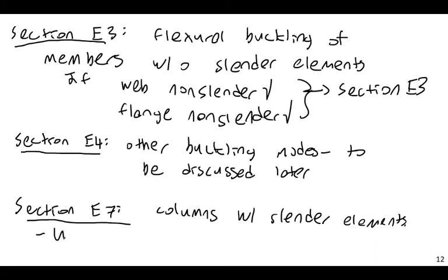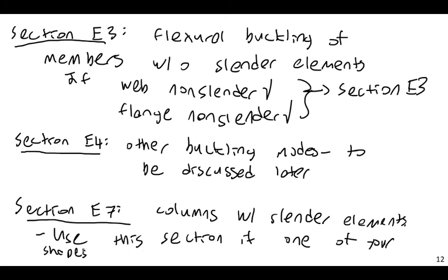You use this section if one of your elements fails your compactness criterion, if one of your shape's elements exceeds the limit from B4.1a. And the equations here are a bit more complex.